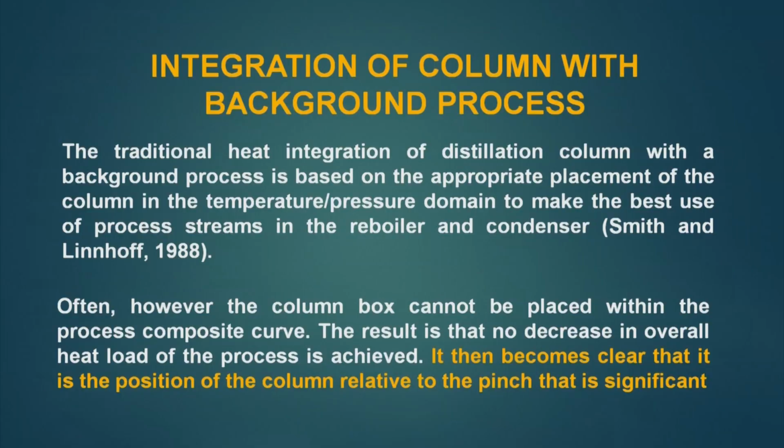Now, let us see what is the integration of column with background process. The traditional heat integration of distillation column with a background process is based on the appropriate placement of the column in the temperature pressure domain to make the best use of process streams in the reboiler and condenser.